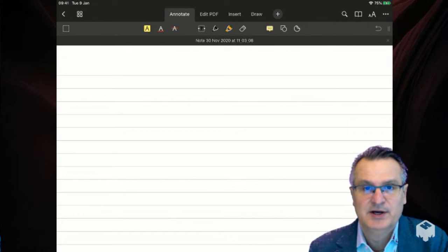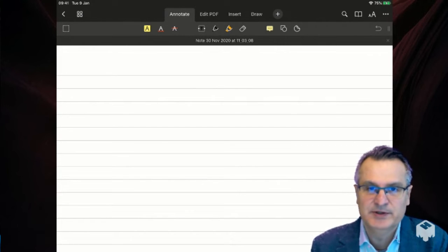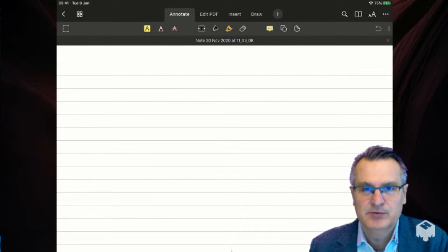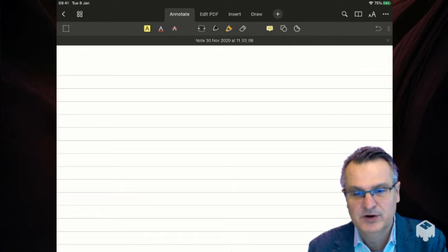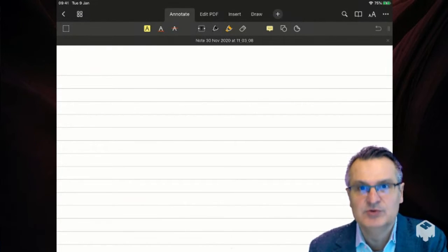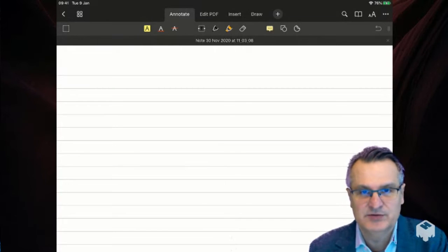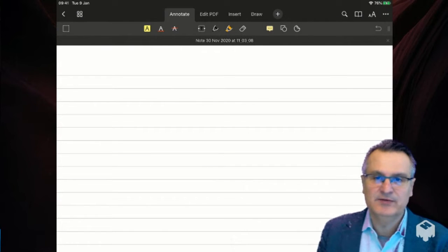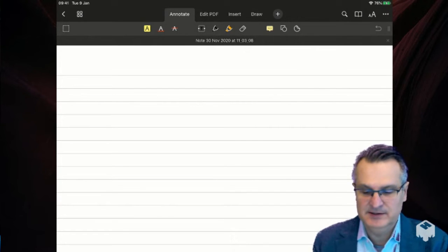versus the stretch, and then knowing that since the material is incompressible and isotropic and so on and so forth, there would be a relationship between the stress and the stretch, and using the data to fit the curve to the prediction. And the prediction depends on W. You don't know W, you don't know the strain energy for that sample. So you have to guess it by looking at the data.